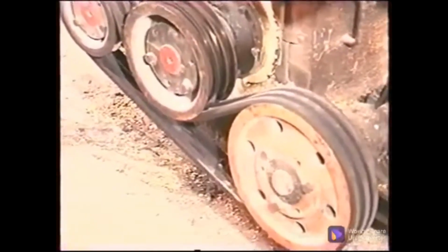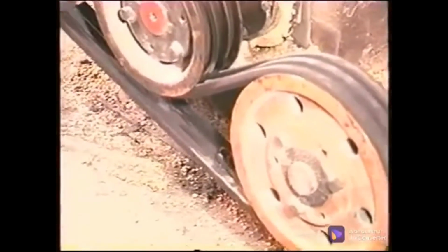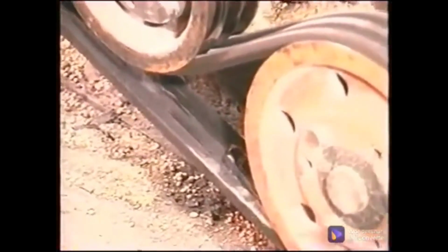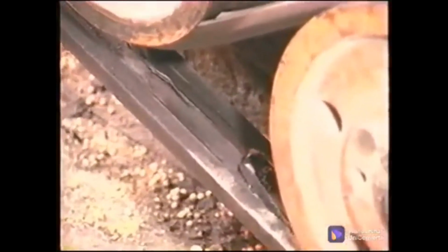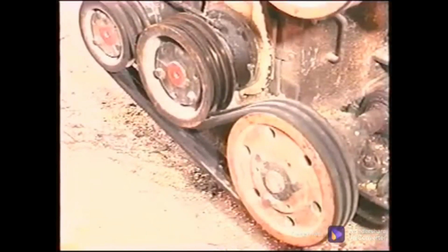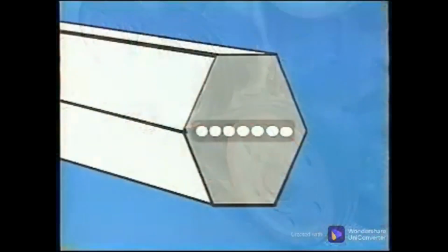The belt drive on this machine uses 3 belts that must drive sheaves on both sides of the belt. These are the double V belts. One belt is bad, having separated and lost a long section from one side. A sheave configuration like this puts tremendous stress on a belt because both the top and bottom side of the belt are subjected to compression and tension. For this reason, the reinforcing cord is in the center of the belt.